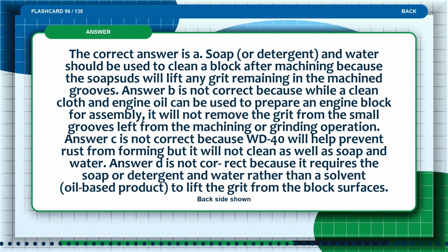The correct answer is A. Soap or detergent and water should be used to clean a block after machining because the soap suds will lift any grit remaining in the machined grooves.